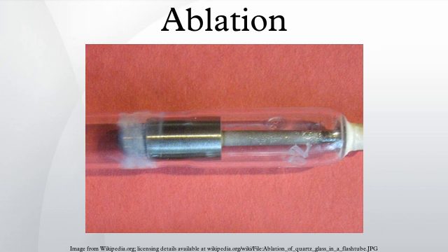Spaceflight. In spacecraft design, ablation is used to both cool and protect mechanical parts and/or payloads that would otherwise be damaged by extremely high temperatures. Two principal applications are heat shields for spacecraft entering a planetary atmosphere from space and cooling of rocket engine nozzles. Examples include the Apollo Command Module that protected astronauts from the heat of atmospheric re-entry and the Kestrel second-stage rocket engine designed for exclusive use in an environment of space vacuum since no heat convection is possible.